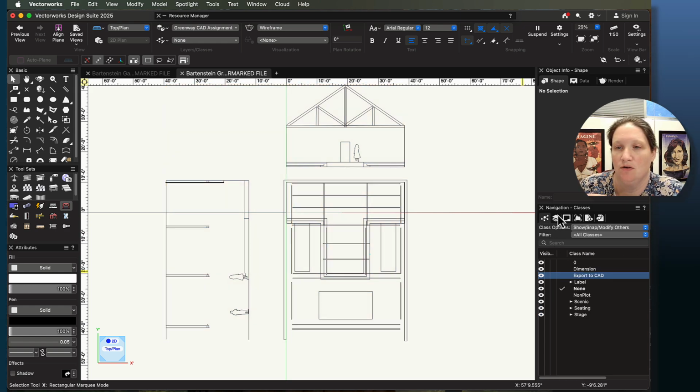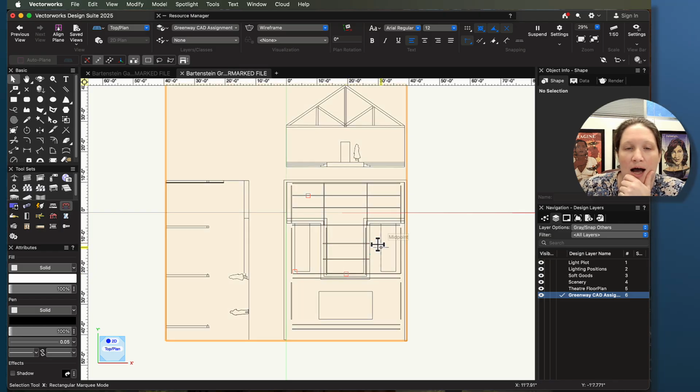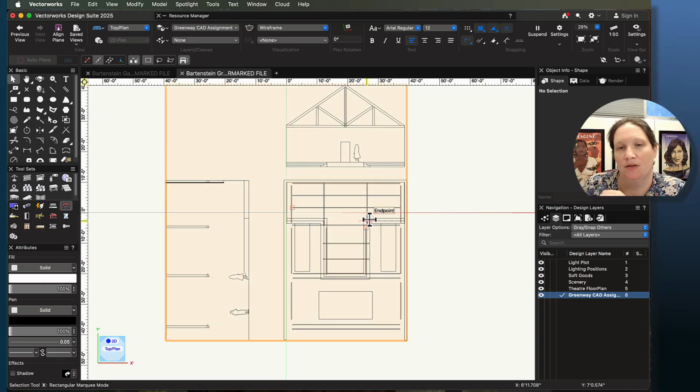So we're going to now trace this theater in the context of the work that we're doing. I want to choose a position to be the X and Y axis for our theater. And I'd like to then align the space with that X and Y axis for the actual drawing. So right now, 0, 0 is in kind of a random place, which is not the best. So I am going to choose a center point of the drawing. I usually make it where the center line crosses the plaster line. And I'll align my drawing to that position.